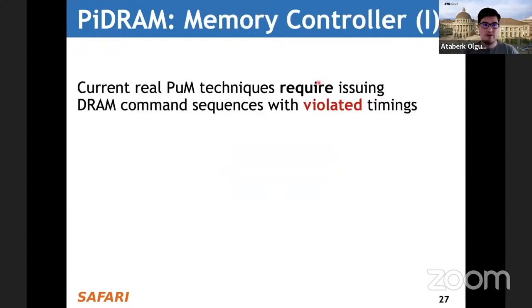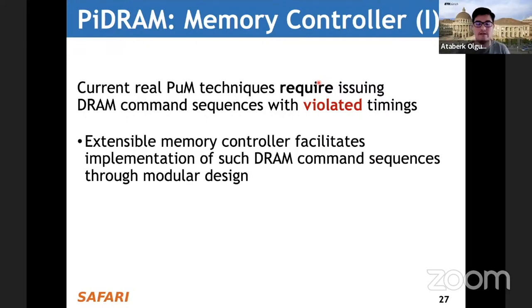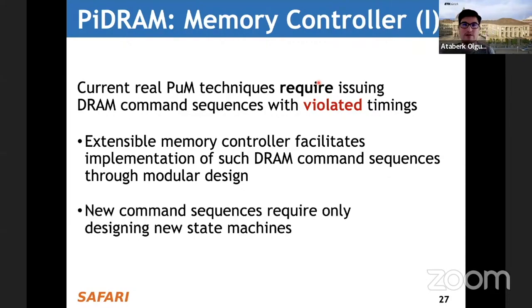I will talk about the memory controller first. Since the real processing-using-memory techniques that I described require issuing DRAM command sequences with violated timings, we develop an extensible memory controller that facilitates implementation of such techniques through modular design. What I mean by that is new command sequences require a minimum amount of changes, so developers can easily replicate the existing code to complete them. Specifically, this will require adding new state machines in our implementation.